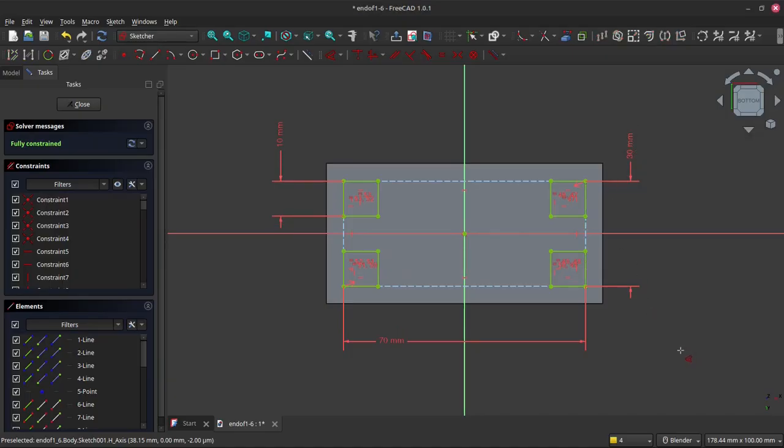But let's consider what we would need to do if we wanted to go back and revise the width and length of our table. We would have to make changes to our original sketch for the tabletop, and then change these length constraints in this sketch as well. Since our primary design concern for the position of the table legs is how far they are inset from the tabletop corners, let's make that the way we constrain their position. I'll delete those length constraints.